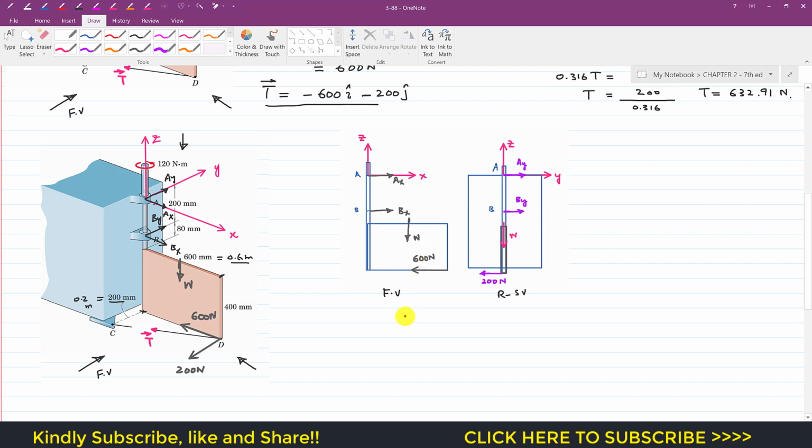Now for the scalar solution, let me write that if we consider the front view, that is the xz plane projection, then we can apply the summation of moments about point A. Since we are interested in finding Bx, we have to eliminate that Ax reaction.